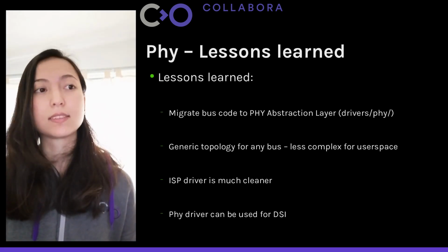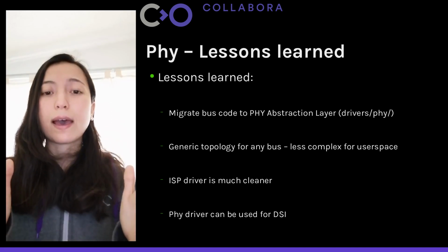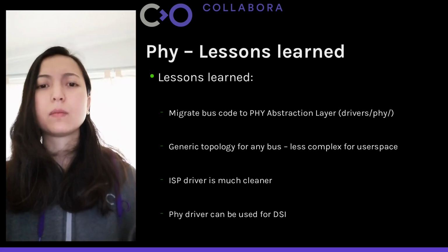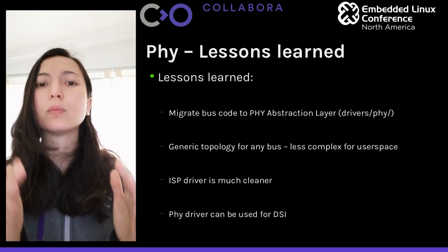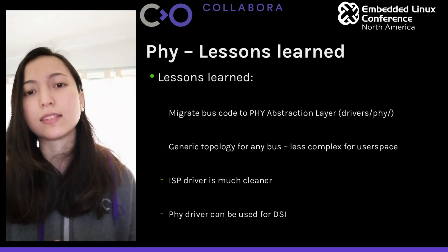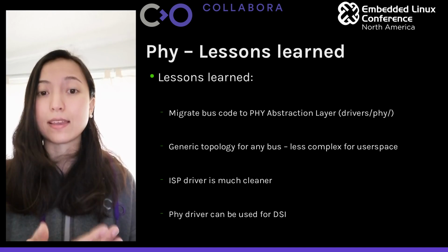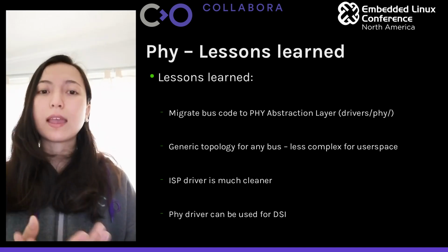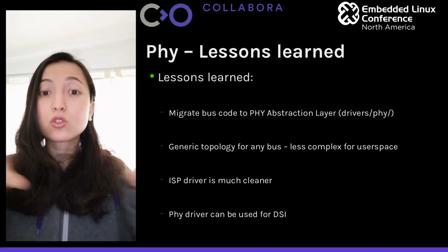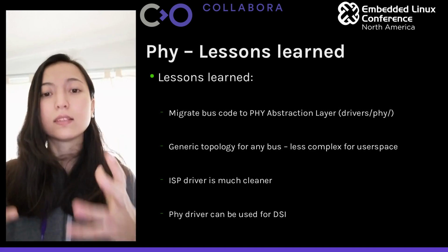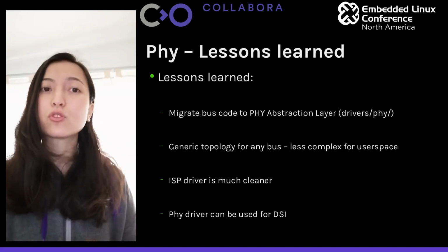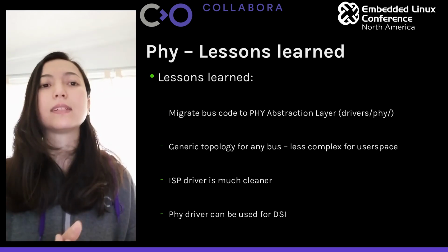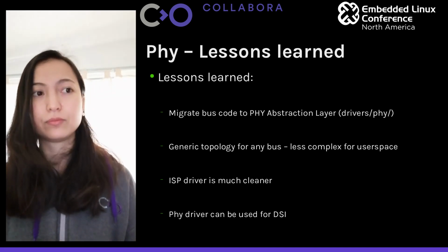Some lessons learned. If you have, so I see this in some other drivers that people post upstream, the code from the bus is usually integrated with the code of the ISP. So if you can separate those in 2 different drivers, one inside the media subsystem and the other one to the PHY abstraction layer subsystem under driver/PHY.